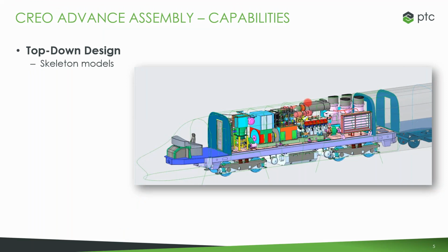Okay, so you're designing this train. This whole profile of the train, all these green curves, maybe this is the outline that you make in your skeleton model. You want the profile of it, so you create these arches. You want to say where the doors are, so you create these surfaces, right? Where's the floor? This is all potentially made in the skeleton model. And then when you're ready for concurrent design, you want to pass this off for different people to work on.